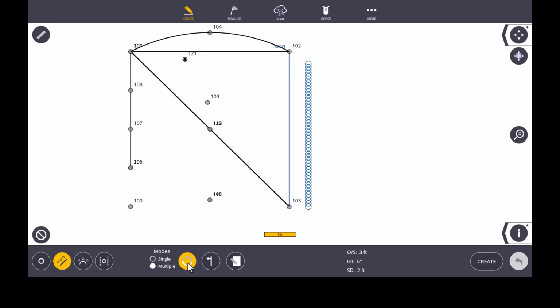Well, if I click this circle, it's going to change our start distance to 0.103. Important to note, and we'll clear again first, whichever point I choose first, if I don't just simply select a line, that will be my starting point. See how start is at the bottom. If I choose 0.102 first, our starting point will be at the top.